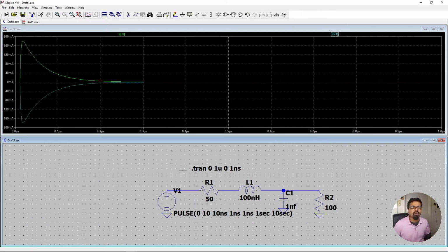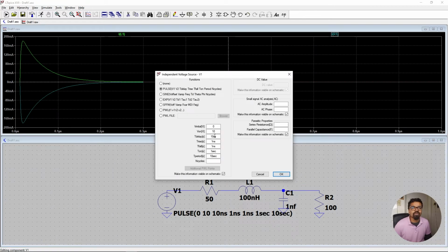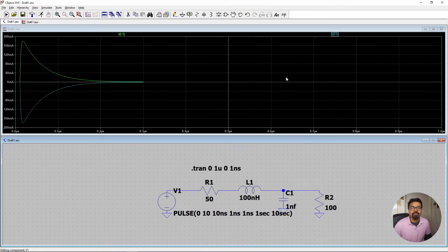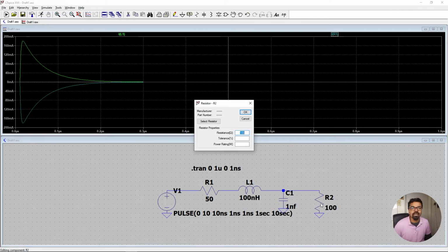So with this resistor, the current flowing through it is I equals V/R. So 10 divided by 100, so we have about 0.1 amp or something of that sort. You know what? I'm going to increase this voltage. This voltage right now is 10 over here. I equals V/R, so 10 divided by, I'm going to make this 1. And then let's see what happens over here.